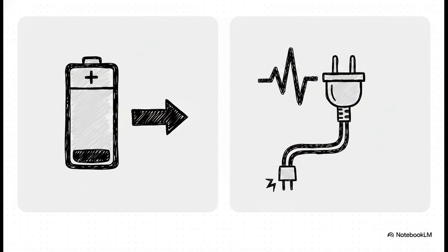Inside your plug, the brown live wire carries this alternating potential, the blue neutral wire stays at 0 volts, and the green and yellow earth wire is purely there for safety. If a fault suddenly makes a metal appliance casing live, that earth wire directs the current safely down to the ground, and that sudden spike in current blows the fuse, instantly cutting the power.